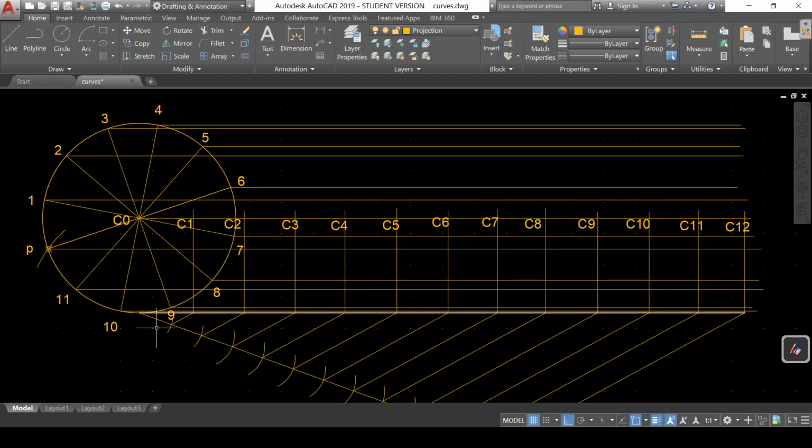Now we have given the names to the points starting from P onwards. Now when this is rotating or rolling for 1/12th revolution, what will happen to P? P will move here, and here another point will come somewhere in between 9 and 10. Okay, so we are not interested in the contact point now. Whatever is the contact point, the P will advance on the locus of these points after every 1/12th rotation, and the center will move to these locations after every 1/12th revolution.